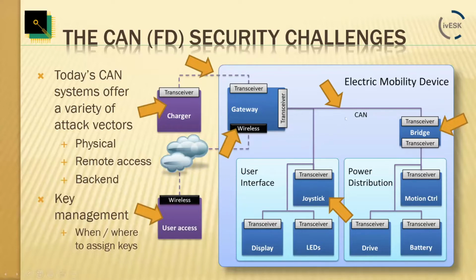So it's really about more protecting once somebody comes in from the outside, either with a sniffer, and is able to read and write CAN messages from the outside. How can we protect our system here? There are quite a few technologies available that can be used on CAN already today, and those we'll have a look at.